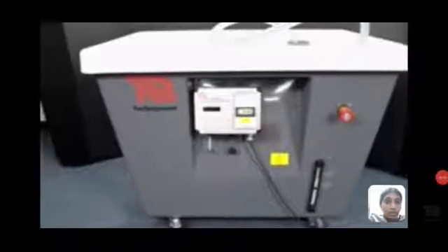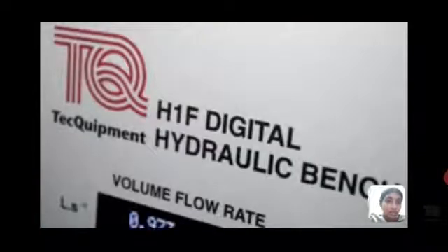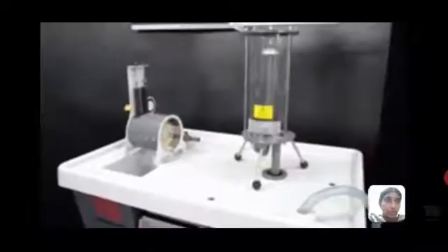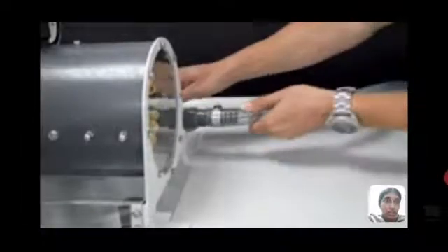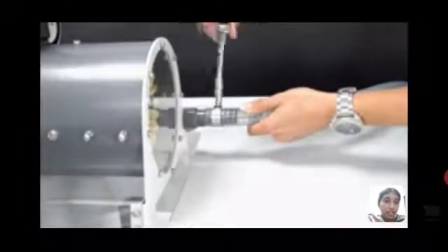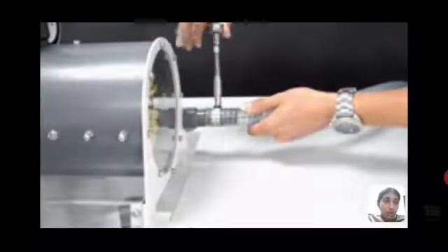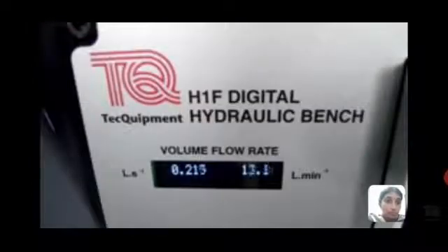Now here you can see Techupman's digital hydraulic bench apparatus. It is a mobile self-contained bench with recirculating water supply. This type of digital hydraulic bench can be connected with any type of flow meter where flow measurement can be done. Here you can see the digital display which measures the volume of flow per second or per minute. As it is a digital display, it is easier to measure, and measurement can be done very quickly.